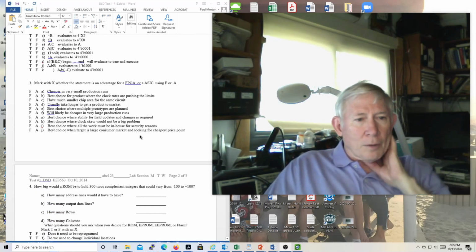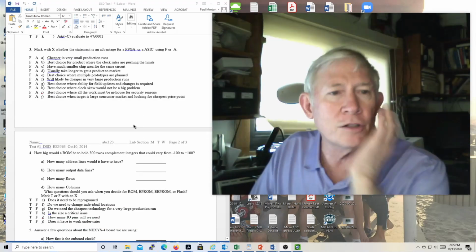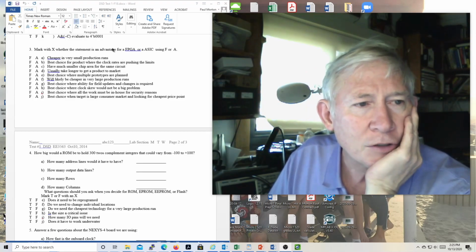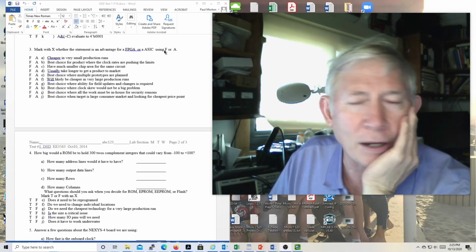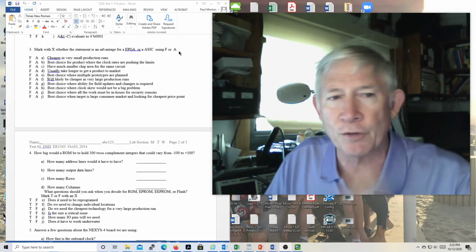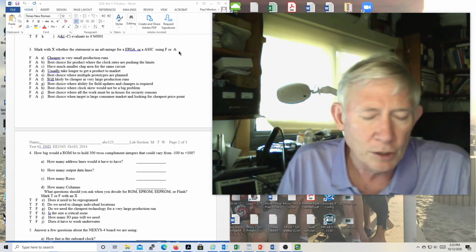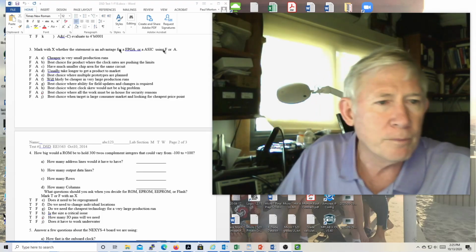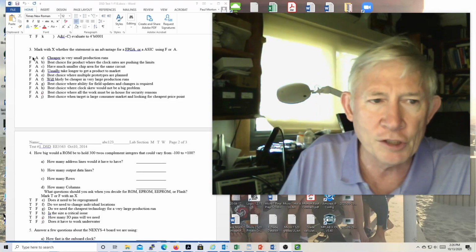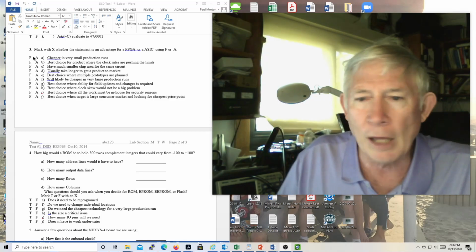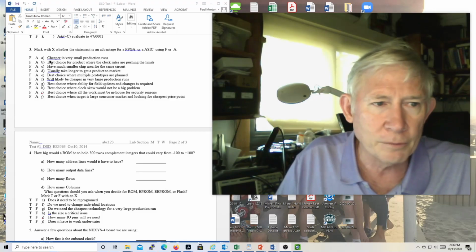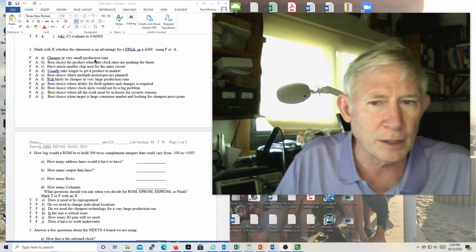All right. Mark with an X whether the statement is an advantage for an FPGA or an ASIC using an F or an A. So F means it's an advantage for FPGA, and A means it's an advantage for an application-specific integrated circuit, which would be just a regular integrated circuit or even a mask programmable integrated circuit. All right, cheaper in small production runs. Clearly an FPGA. If you're going to do lots and lots, you can afford to have the foundry do these for you. But if you're not going to do lots, you really can't afford to go through the cost of firing the foundry up to make your chips.